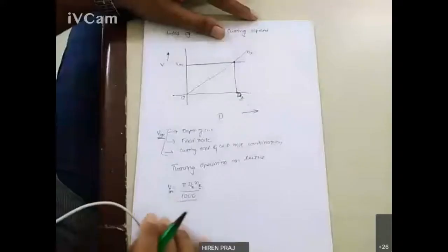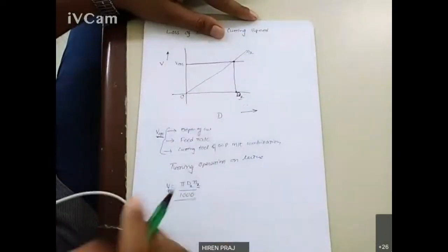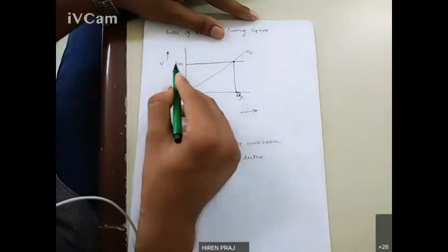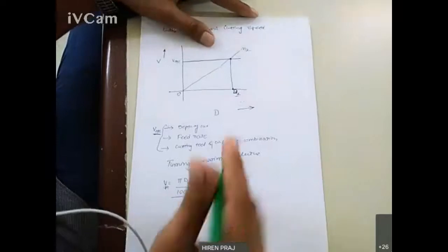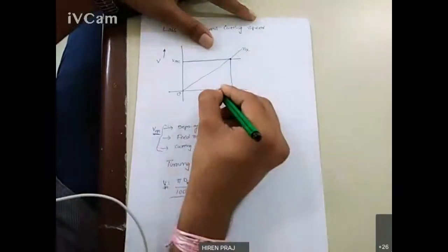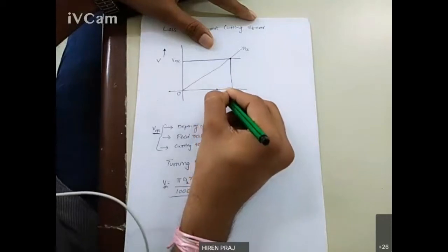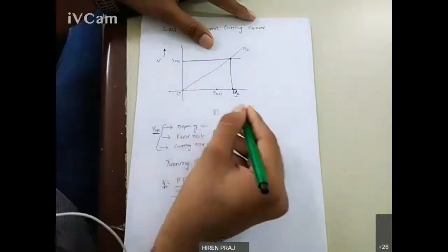Okay, so this relation will give us the Nx line. This Nx is for particular diameter Dx to obtain required cutting speed. Similarly, now if you take the next diameter Dx plus 1, in this direction diameter is gradually reducing because we are cutting material, right?